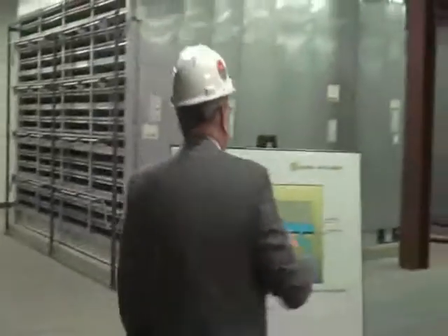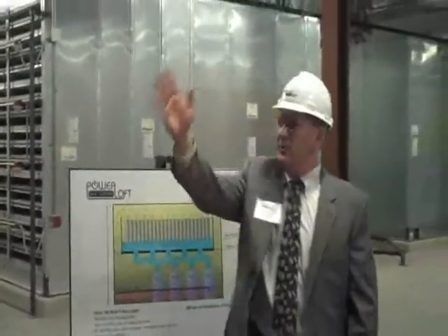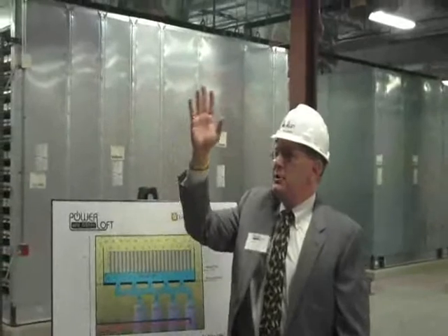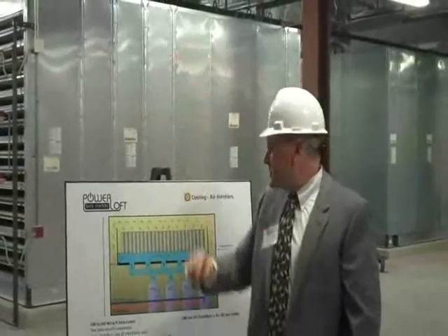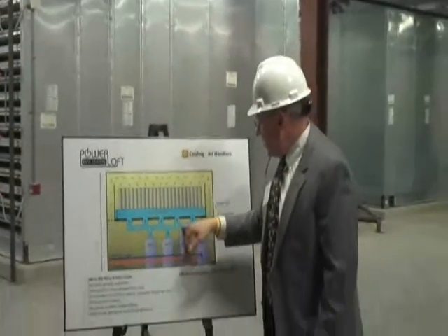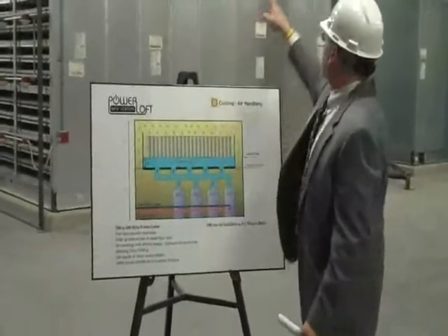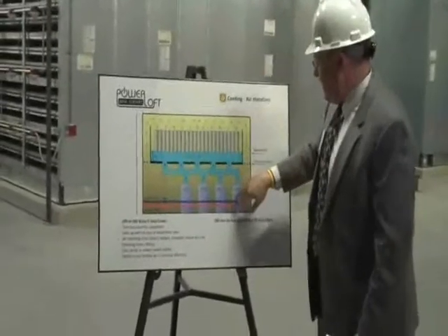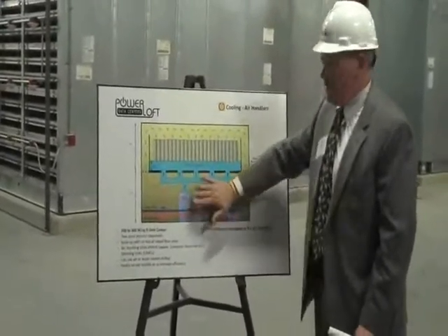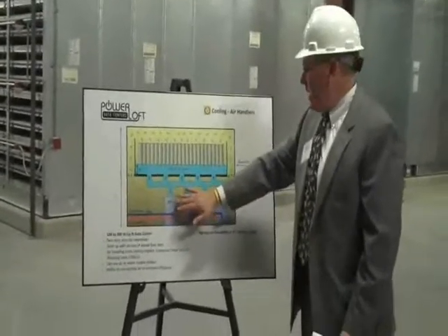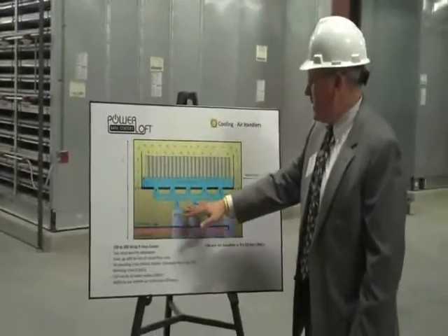They're all tied together in a bay. A bay goes the width of the building, and each tenant space is a bay or multiple bays upstairs. We push the cold air up together. They're all tied together so that you have N plus 1, your required amount, plus 1 additional as a redundant. And if any one were to go down, the other three can pick up.